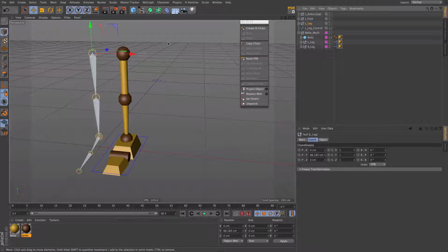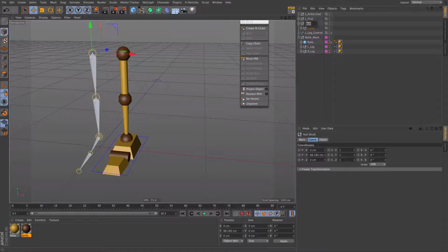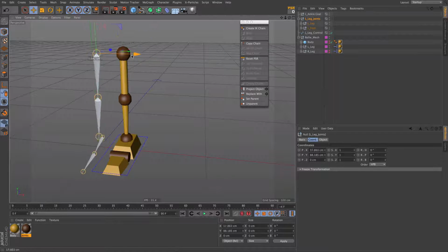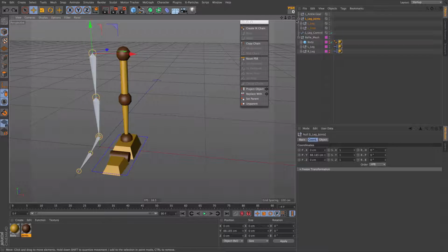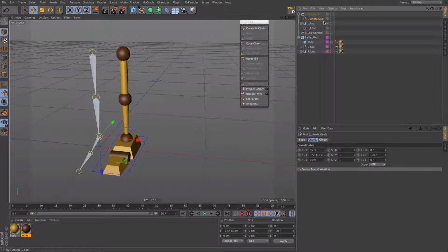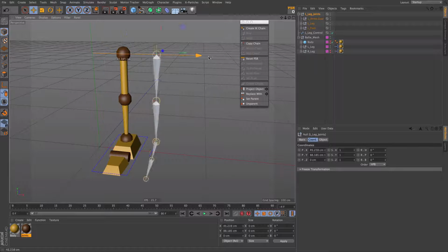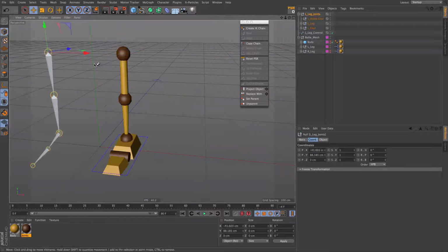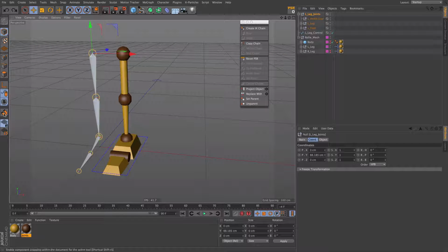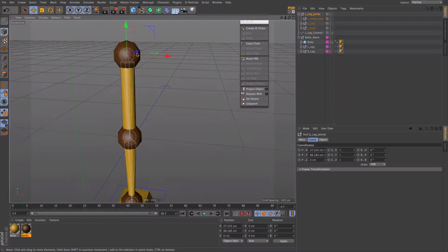I'm going to select the leg, group it on itself, and name this left leg joints. Then I'm going to parent the left foot on the same group, so I'm taking everything with it, and I'm going to drop the goal also under this, so it's taking the whole rig. And I'm going to enable snapping and bring it right in the middle of the left leg.